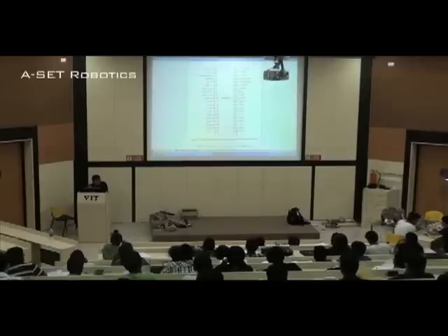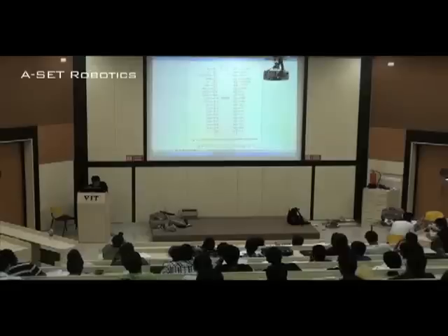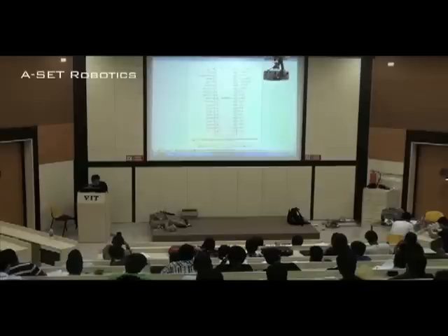This is a very important thing, that from the left of this point, the counting of the microprocessor pins would start. So if you hold it the other way around and want to see where the counting is, you have to look at this point to make out where the counting will start.